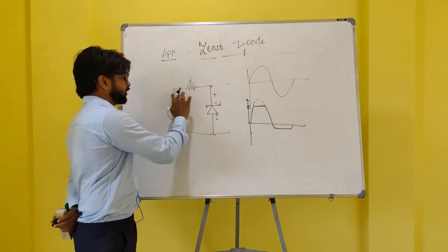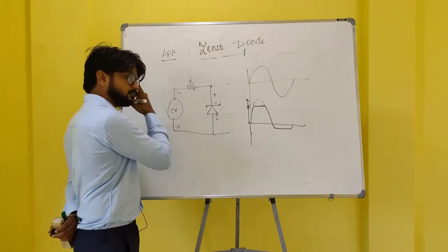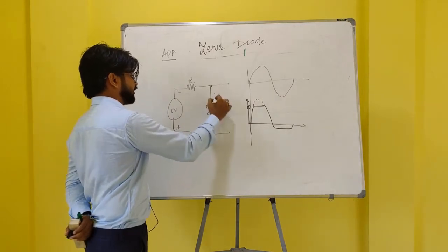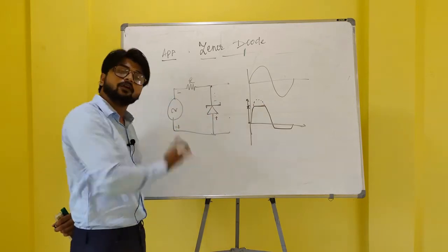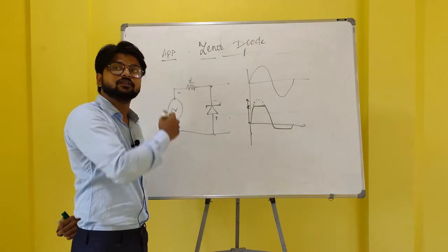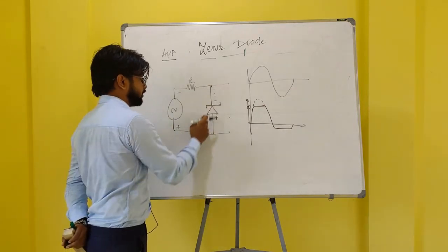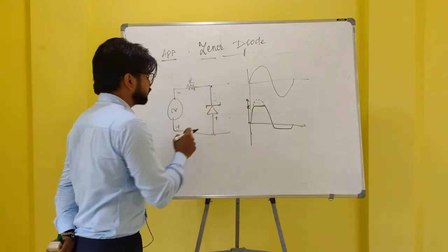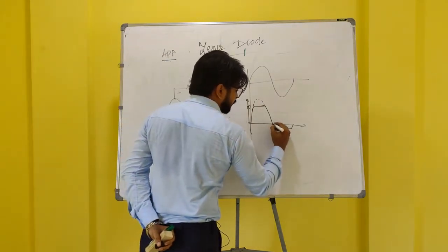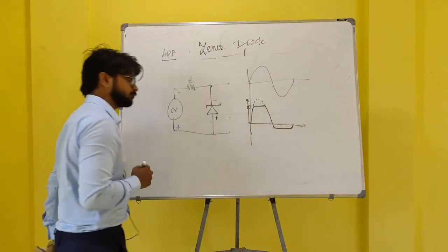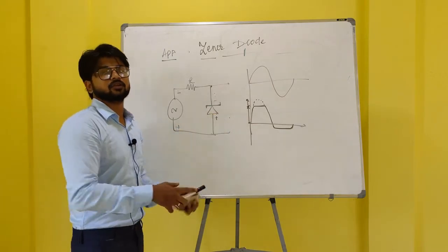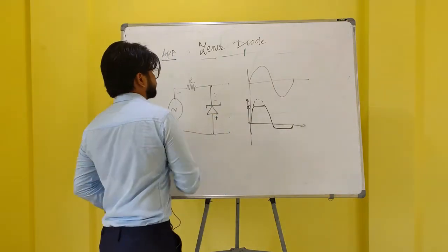Now in the negative half cycle, this is forward bias, this is negative and this is positive. So in forward bias condition, this behaves as a short circuit. Due to a voltage drop of 0.7 volts, a little current is passed. This circuit will also be explained in Multisim in the next section.